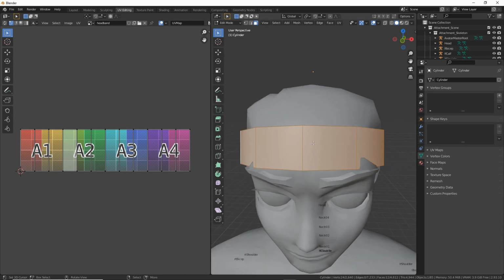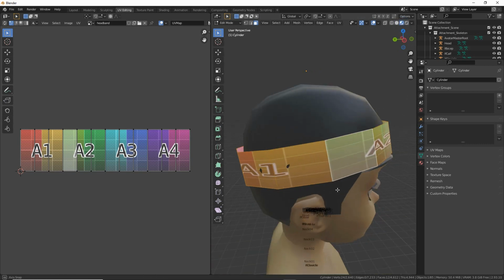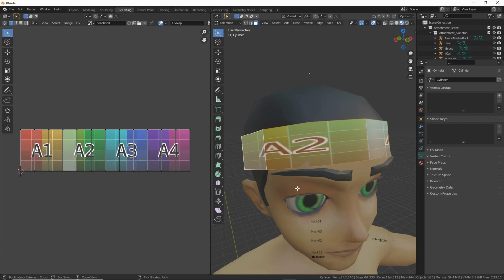And we're in solid mode at the moment, so we want to switch to textured preview. So given the shape of our object, it's very thin versus being very long. So what that means is the UVs are stretched. So what we can probably do is halve this image.